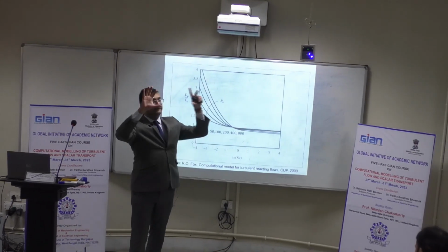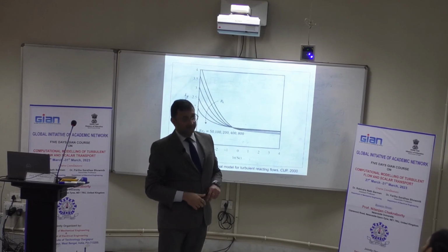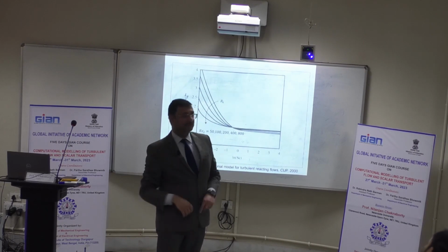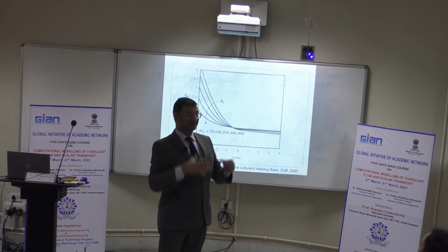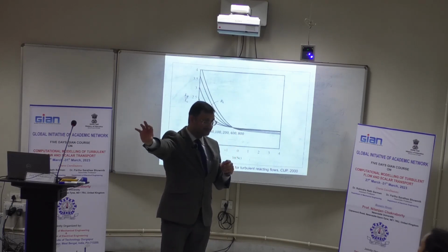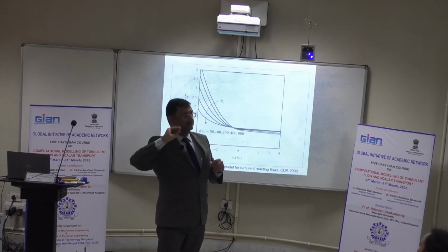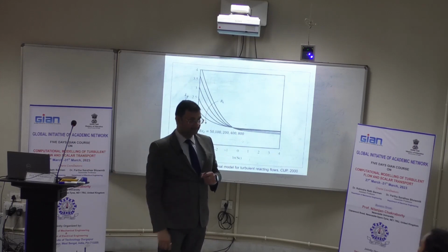Physically, I can have different size of blobs to begin with. If I allow them to develop under turbulence, eventually the integral length scale, irrespective of what I started with, will become of the order of turbulent length scale.